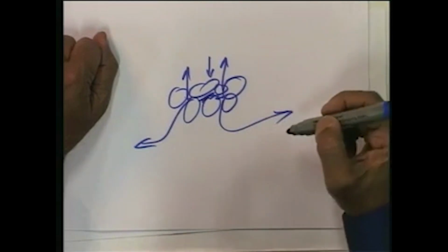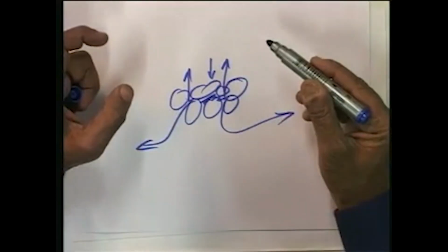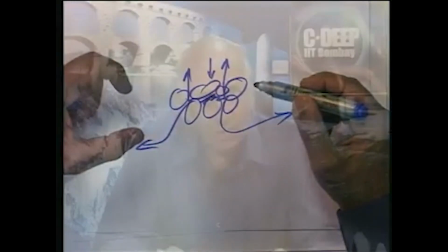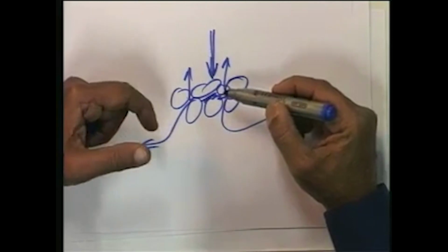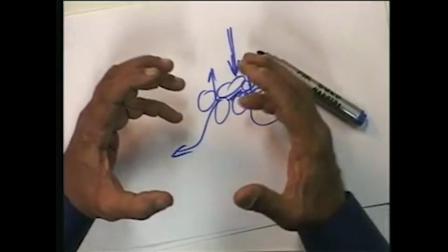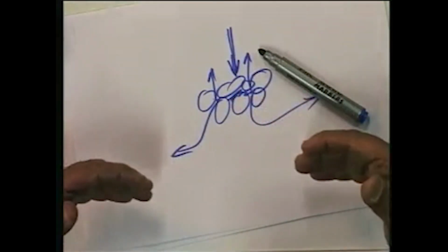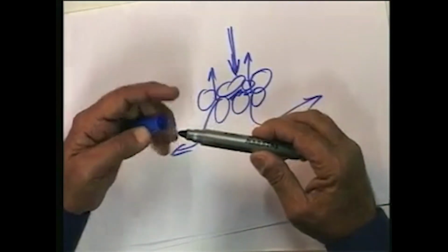Now, when the water flows out, the particles are readjusting themselves, and therefore, water cannot take load. Since it is not residing in its original position, since it is moving out, what really happens is the applied load ultimately gets transferred to the solid grains as the water goes out, again gradually, and as the particles come closer and closer and come into contact with each other, a distribution of the load finally takes place in the form of certain kind of stress distribution. So, that is what is known as stress transfer. More of it we will see a little later when we look at a mathematical or a physical model which explains how this stress transfer is taking place.